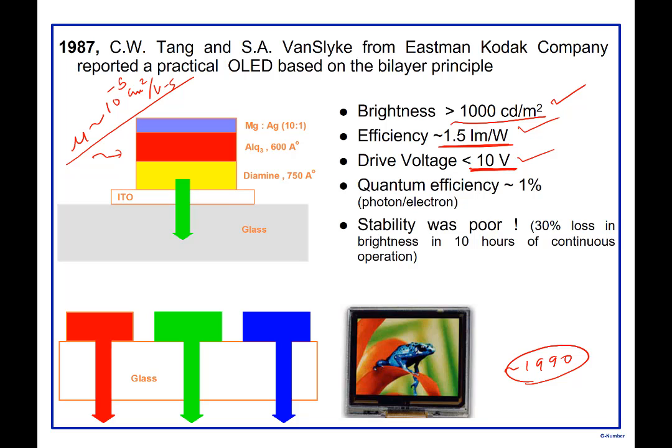So this is where I think we carry certain numbers in our mind, 1,000 and 500 and things like that. They are required for some applications. For an OLED, we'll do the calculations and show it to you that you don't require very high mobility. You don't require very high mobility, and therefore these amorphous materials that I'm depositing on glass have low mobility, but they're okay. They're sufficient. They're sufficient to give me enough light and enough efficiency to compete with the existing technologies and make a full display.